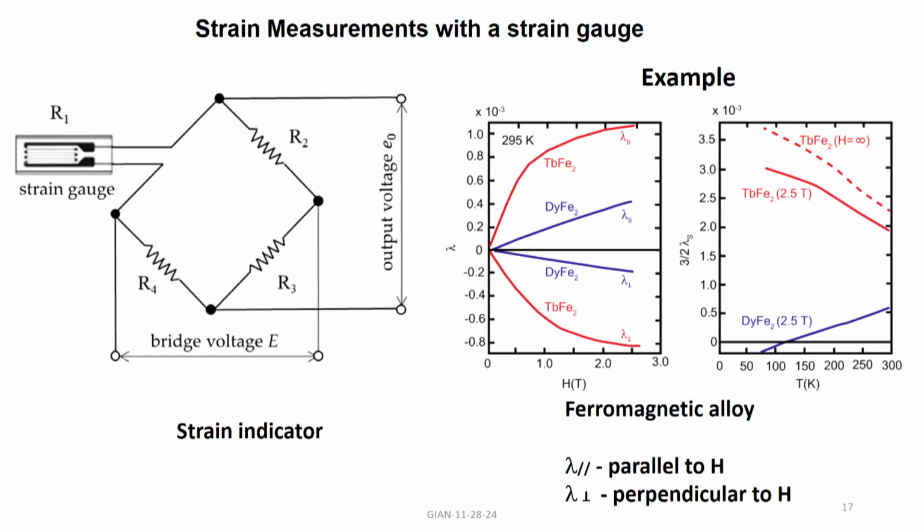And we know about this, I showed this earlier, this is the strain gauge, it forms a Wheatstone bridge. So, the bridge output goes to the strain indicator, and whenever there is strain, the resistance of this arm will change, leading to a condition away from balance. The strain indicator will correct for that and will produce an output which will show the strain in parts per million. Okay. So, you can directly read what the strain is, and it can be measured parallel to the magnetic field or perpendicular to it, it does not matter.